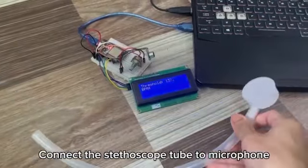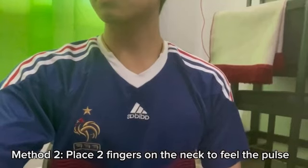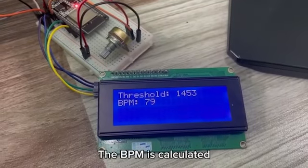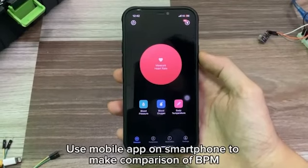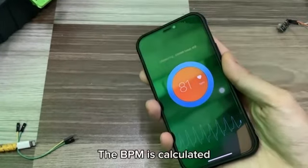Now we'll test the setup using two methods. For method 1, we place the stethoscope on our chest and let it detect our heartbeat directly. For method 2, we place two fingers on our neck to feel our pulse, and we tap the microphone every time we feel the pulse, and the signal detection system will pick up the input. The BPM calculation process will start, and it takes around 15 seconds for the BPM to calculate accurately. The threshold detected is 1453 and the BPM is 79. Through the app, the calculated BPM is 81.